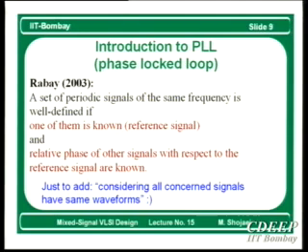What does it mean? It means that in any corner of the chip, if I have data which is synchronized with some clock, but because of delay in the interconnect this synchronization has skewed, and I am able to generate a clock which has a well-defined, well-known phase shift with respect to this data, then I am done, right?